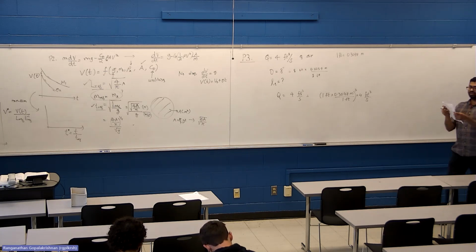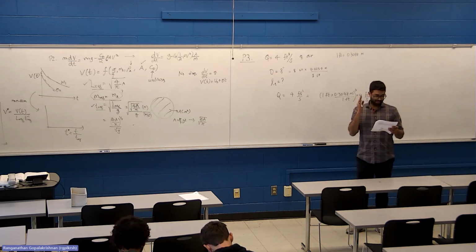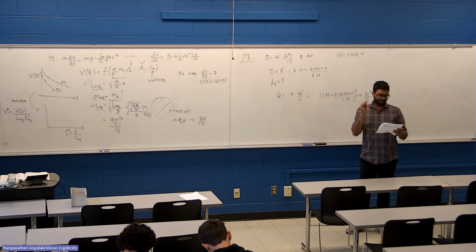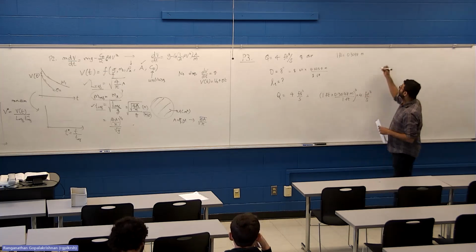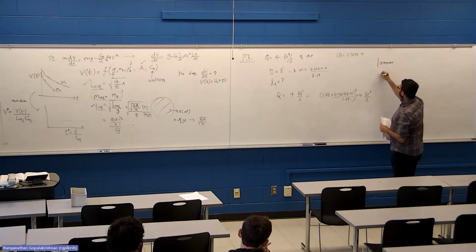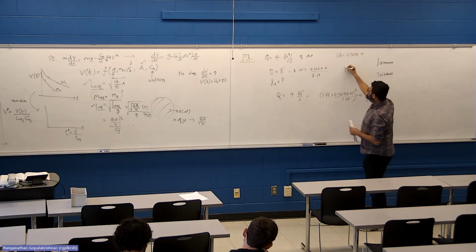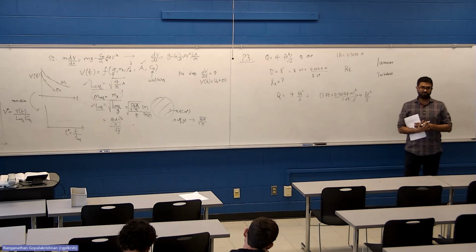See, look at the equation below. The correlation for different laminar flow and turbulent flow is given. It depends on Reynolds number. You need to remember two things: what constitutes laminar flow and what constitutes turbulent flow based on Reynolds number. I'm not going to give you that information. We talked about this for pipe flow. What is the cutoff criteria?